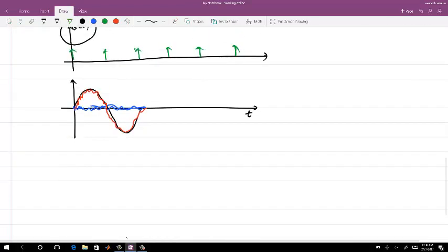So what you do is find how, if I cause any disturbance here, my phase changes. You find all the change in the phase with respect to the different timings of the inputs. This comes under the impulse sensitivity function. So this is called ISF, impulse sensitivity function.